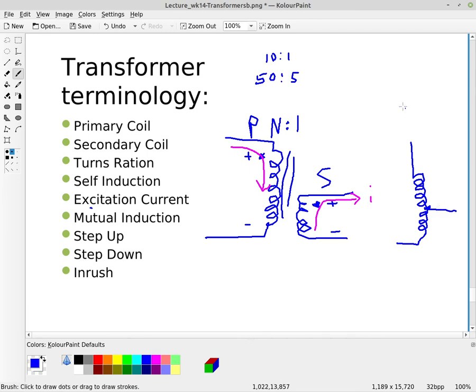This is sometimes referred to as an auto transformer, and it does not have electrical isolation because one side of that transformer is basically ground or electrically connected on both the primary and the secondary side. But most, like the power company transformers, those are all isolating.